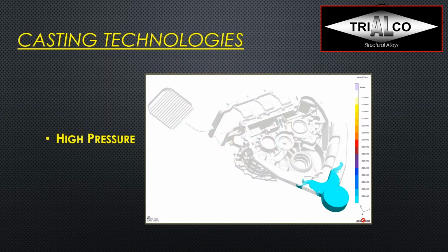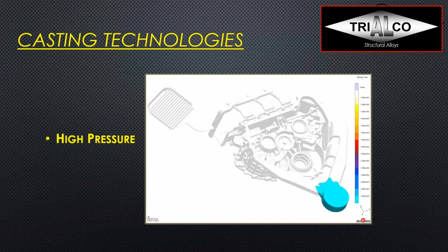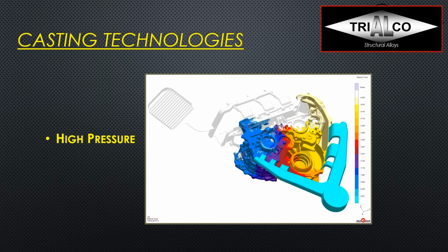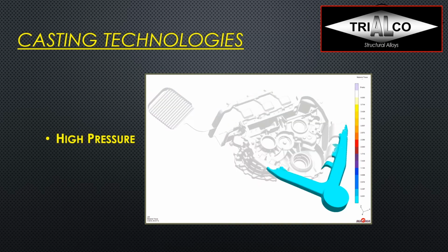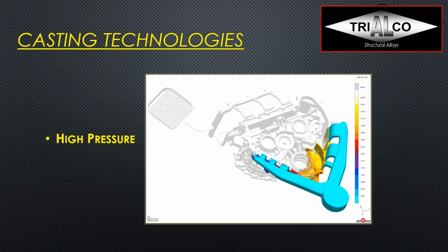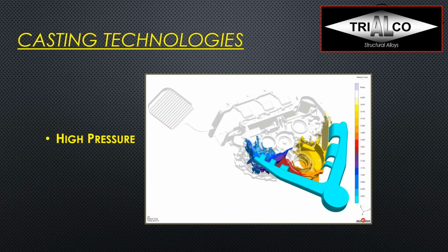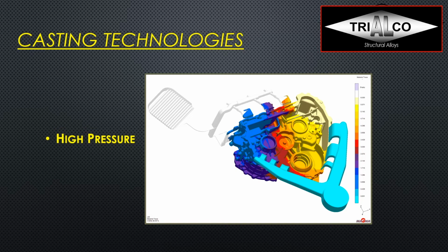Now here we can see a simulation of the high pressure die casting process. This is not real time, and we have actually 3 phases of the high pressure die casting process. The first one, that is shown as light blue, light greenish, is where the metal is in the shot sleeve and the ingates, and that's what we call the slow shot part of the filling process. That usually takes 1 or 2 seconds, but after that, where the other colors start, and each color represents one metal string or stream, and that cavity filling itself is usually just a question of milliseconds. So in this case, it's probably 50 to 60 milliseconds.